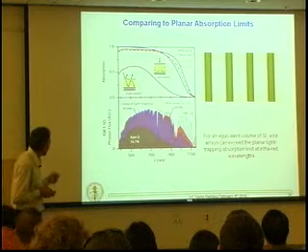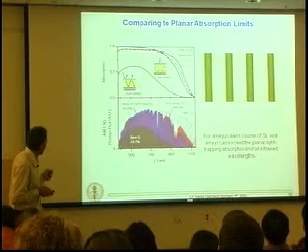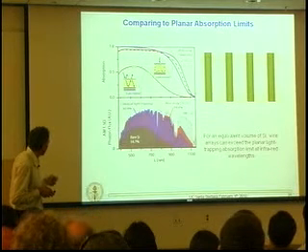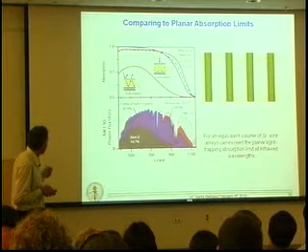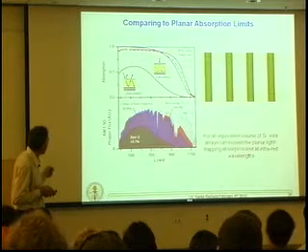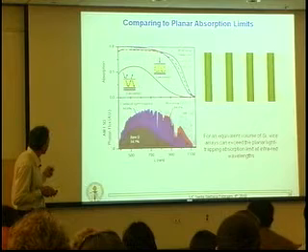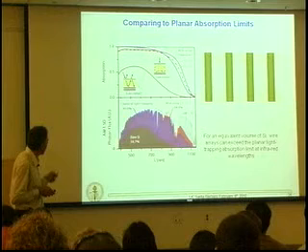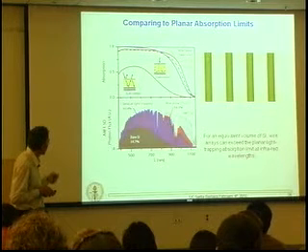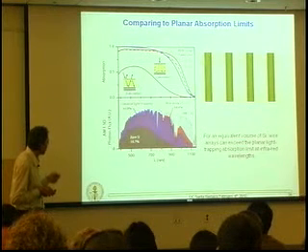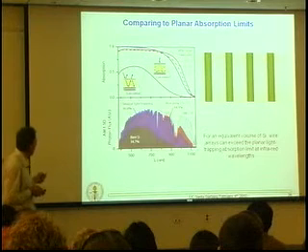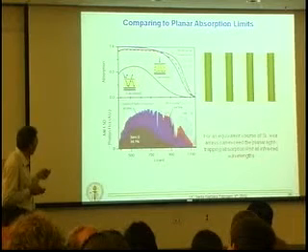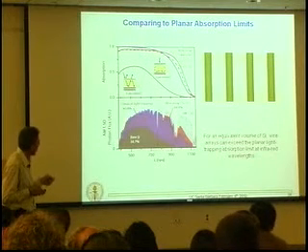When we have a Lambertian back reflector, we find rather interestingly that compared to a specular smooth piece of silicon, we have substantial absorption. But compared to a randomly textured sheet of equivalent thickness, this is the spectral absorption. The randomly textured sheet absorbs slightly better in the mid-visible range. But in the region where silicon has low absorption, we actually have higher absorption in the wire array than we do in the randomly textured sheet. So in some sense, we have exceeded this ergodic limit that was the previously imagined limit in these wire arrays.